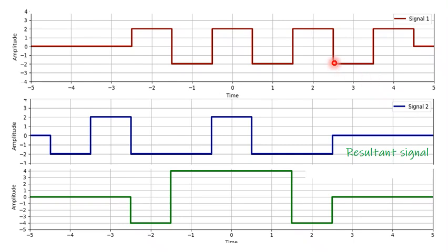Because from 2.5 up to 3.5, the signal has an amplitude of -2, whereas this one has an amplitude of how much? 0. So 0 multiplied by this will result in 0, and then again because this signal is positive again, but this signal is 0, the product of 0 with negative or positive will result in 0. So the final signal is as shown here.